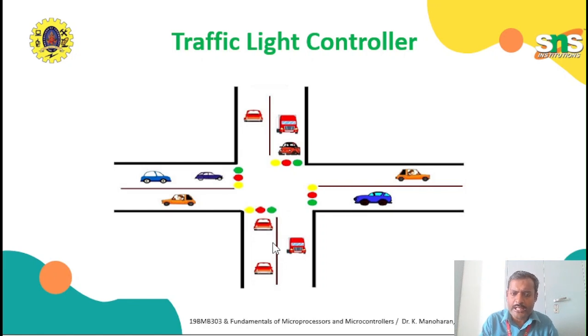After that particular time, we need to turn off the green. We cannot turn on red immediately. Instead we turn on yellow for 5 seconds, and after that we turn it to red. At that time we can change to the next direction, where I can turn on a green. Once this direction is turned on, the vehicles will enter and go straight, and right and left also. The free left can go at any time. The remaining 2 directions only go with their green lights. After this arrangement it goes to the next direction and the next, continuously. After completing all the directions, preference is given for the pedestrian crossing.